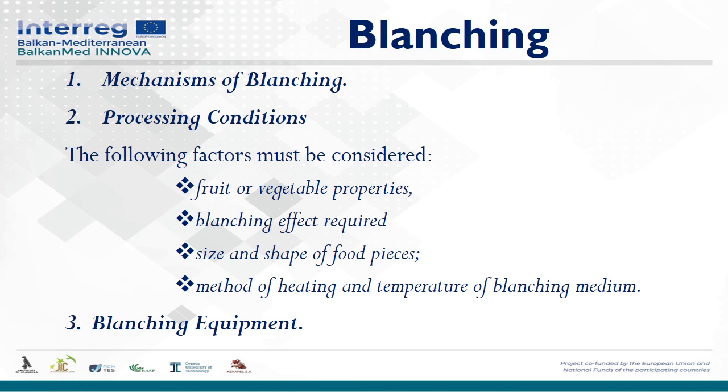Blanching equipment. Conventional steam blanching consists of conveying the material through an atmosphere of steam in a tunnel. In this case, if raw materials are not distributed carefully, treatment will not be uniform. The two main conventional models of hot water blanchers are reel and pipe models.